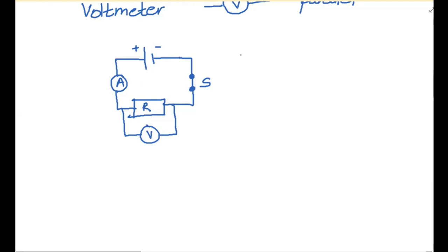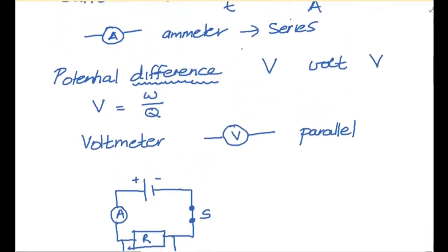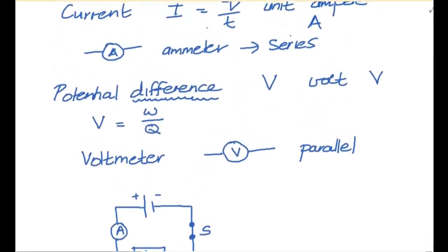Now, because we're going to talk a little bit about resistance and calculating resistance in circuits, while we're here with the voltmeter and the ammeter, note that because an ammeter is placed in series, when someone builds an ammeter, knowing it's got to be in series, they need to make sure that it has a very low resistance.